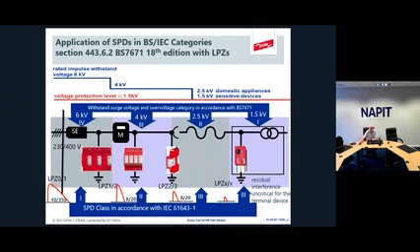The figures in those blue arrows, they're mentioned in section 443. That is voltage withstand. So at the origin, that's the most robust location. That takes 6 kV. We're interested in protecting appliances, which are rated at 2.5 kV. And you'll see that figure quite a lot within the standard itself.